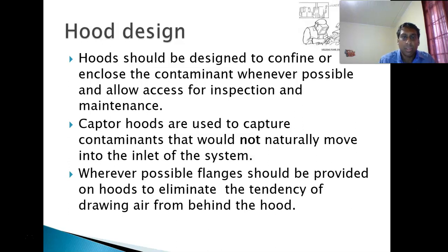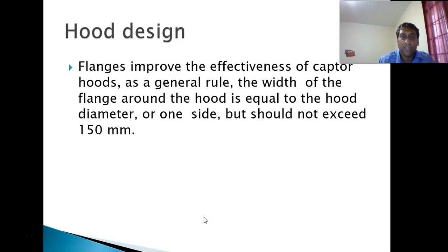Capture hoods are used to capture contaminants that would not naturally move into the inlet of the system. Whenever possible, flanges should be provided on hoods to eliminate the tendency of drawing air from behind the hood. So what is a flange? You'll pick it up on this slide here. Flanges improve the effectiveness of capture hoods. As a general rule, the width of the flange around the hood is equal to the hood's diameter or one side, but should not exceed 150 millimeters.